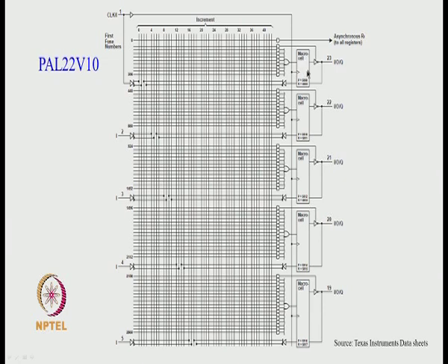So this is a macro cell which includes a flip flop, and also includes a bypass. Now you can see that the feedback here can come from two places. Internally it can come from the flip flop, but if you are bypassing the flip flop, then that feedback is not useful. Then this pin is fed back. In that case, like 16L8, it can be used as output, input, IO, cascading, all that applies.